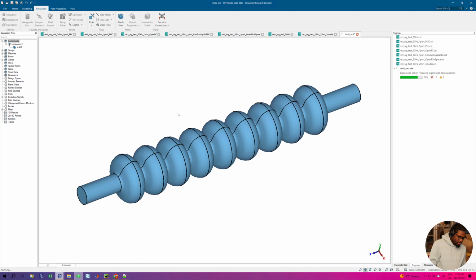So what I'm going to do now is turn on adaptive mesh refinement. I do not want to manually make the settings. So it's going to run until it converges, and I'll define the frequency variation as 1e to the minus 6. This is the accuracy that I want, and for how many passes, maybe 8 or 10. I imagine it's going to take quite some time, so I'll pause.